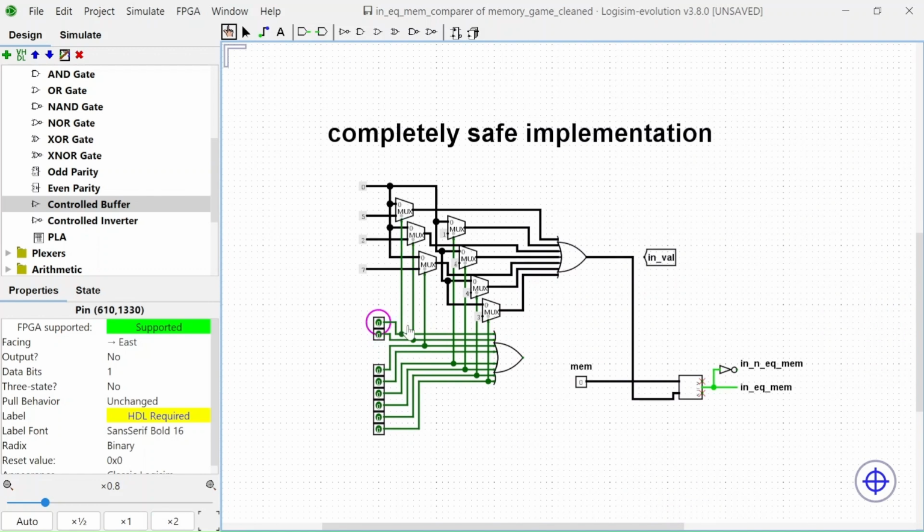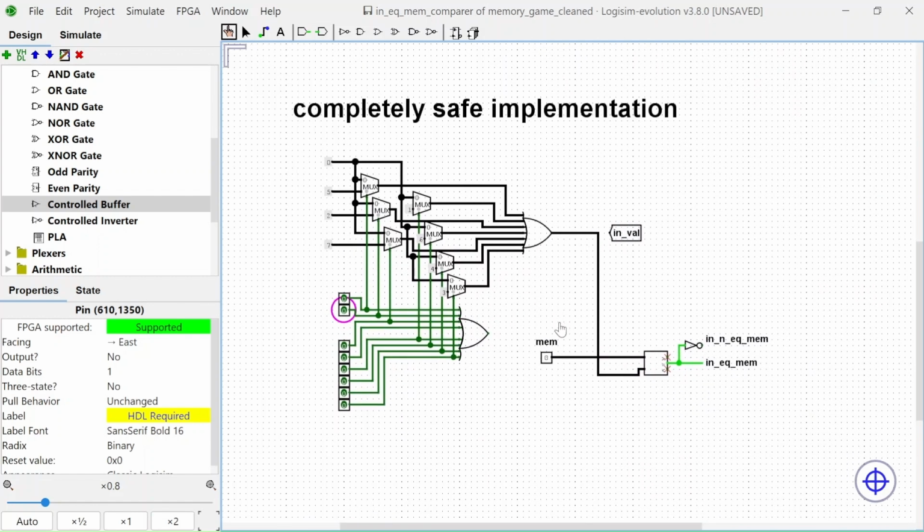This version just lets a constant through to be compared to memory using a mux. If multiple buttons are pressed, the result is just ORed together. The default value of inval is 0 and stays 0 if no button is pressed. However, this is fine because the comparison's result will only be used after an input button has been pressed.